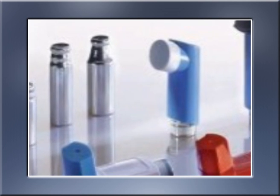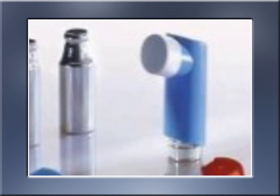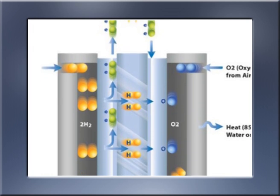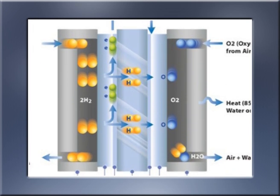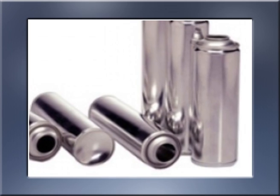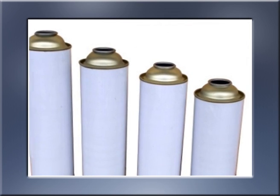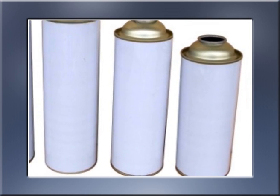Most aluminum containers are manufactured by an impact extrusion process that makes them seamless. Therefore, they have a greater safety against leakage, incompatibility and corrosion. Another material is stainless steel. It is used when the container must be chemically resistant to the product concentrate. The main limitation of these containers is their high cost.